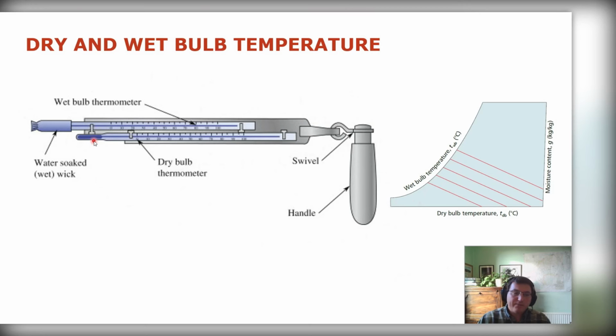On the other hand, if the air is saturated, the amount of vapor in it is already high enough that it provides a partial pressure of vapor equivalent to the saturated pressure at this temperature, then there will be no evaporation at all. No matter how hard they spin it, some of it may just fly out kinetically, but there will be no actual evaporation. Therefore, there will be no cooling effect. Then my wet bulb temperature should equal my dry bulb temperature, right?